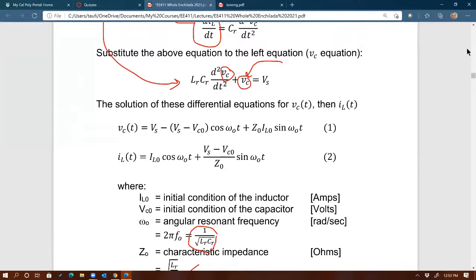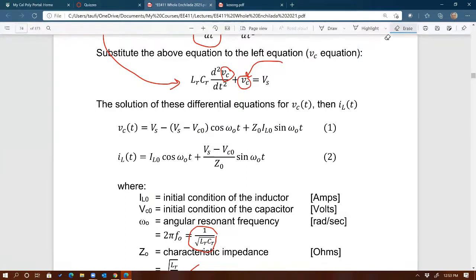In any of these 4 cases, we want to make sure that we always end up with a sinusoidal waveform for both capacitor voltage and inductor current. If we are sure that we always end up with a sine wave, then we should be able to use this in our DC to DC converter, right? Without having to worry about initial conditions, okay? So let's do that. Let's do the first case.